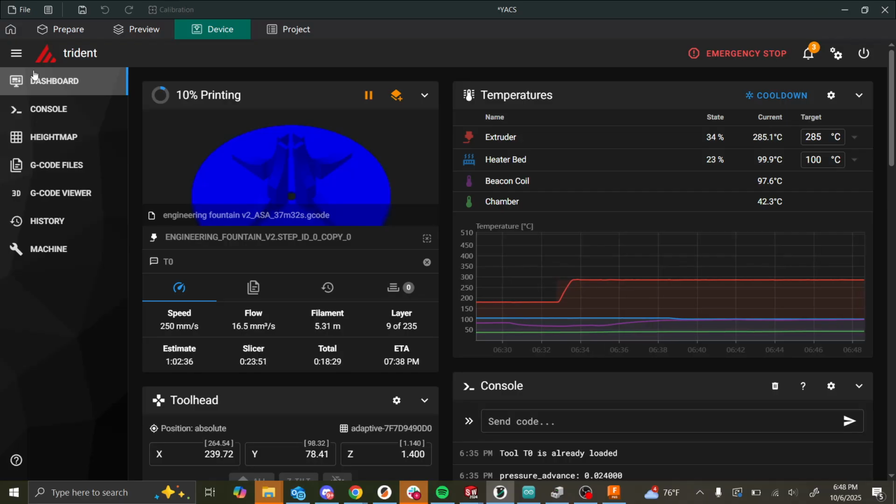Yeah, so you're seeing the first layer, how the first layer is, and this hole is supposedly the right dimension to put the filaments, and then the test over here. These are the overhangs. Oh yeah. And then how it interacts with holes, and there's straight up bridging because there's no curves. And this at the end is testing to see how good your cooling is, because if your cooling is really bad, the whole thing looks like this. Yeah, if your cooling is good, the whole thing will look like this.